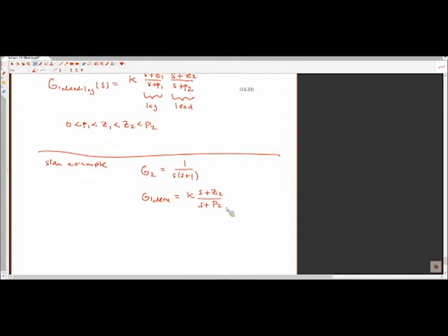Keep in mind that alpha, you are looking at a transfer function. You're trying to understand what is the steady state error for the system given that you have G1, G2 identified. So we've done half of G1. We've just done the lead section here. So G1, G2 is going to be equal to this unknown transfer function yet, (alpha T S plus 1) over (alpha T S plus 1). This is your lag. You have your lead already defined because you built this and it works great. And this would be the transfer function you're evaluating when you're evaluating the steady state error for the system.